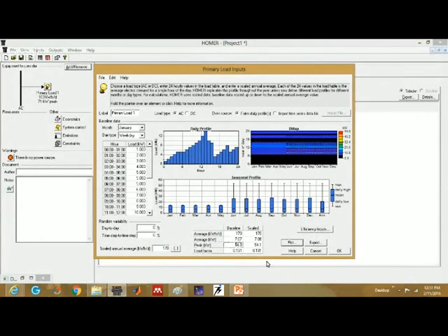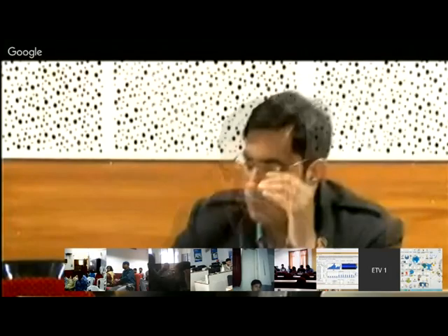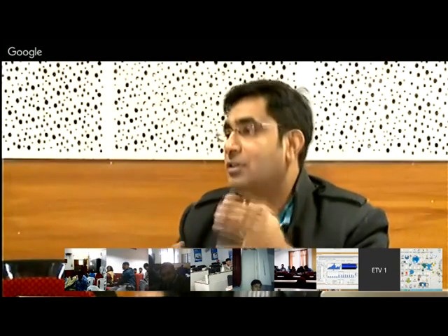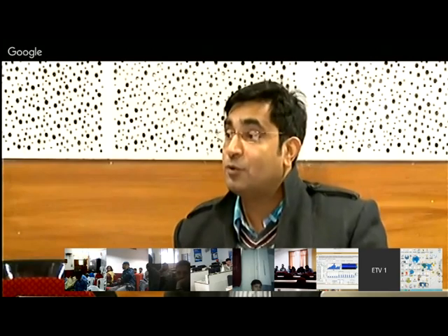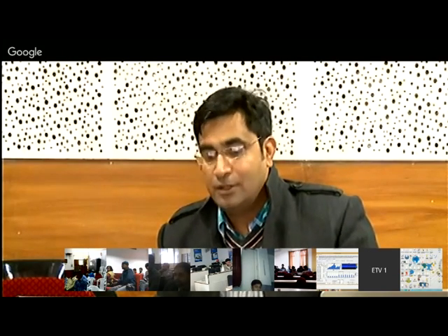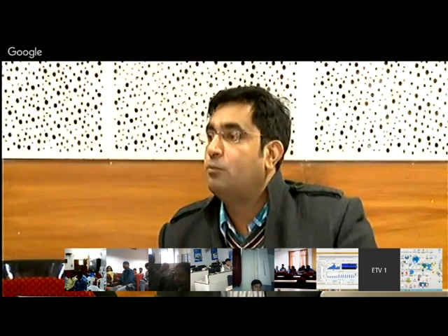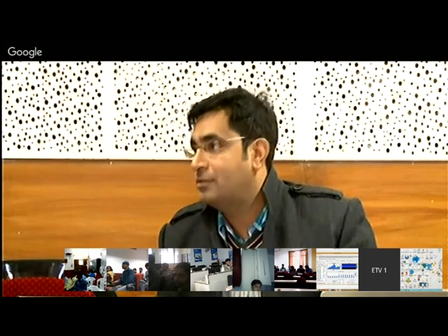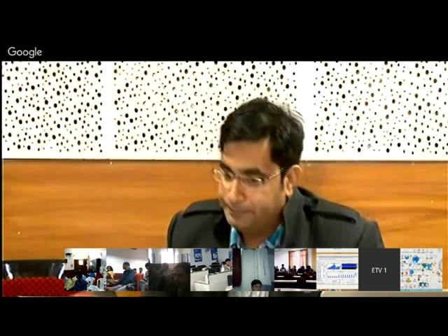So the problem with this optimization system is that we have to consider that 54 for one day also. According to that, if we want to meet all that demand of 54, and let's say the variation in load is such that one day the load demand is 54, and the routine average demand is 7 only. Now see the difference. We have to design the system according to the 54. And if you design the system according to the 54, so many kWh are going to be wasted because we will have excess electricity, right?